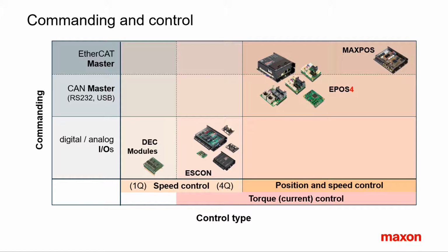In summary, the pure speed controllers DEC and SCON are commanded by simple digital and analog IOs only. The position controllers, EPOS and MaxPOS, need a master system with more sophisticated bus communication. Simple IOs will not do the job.